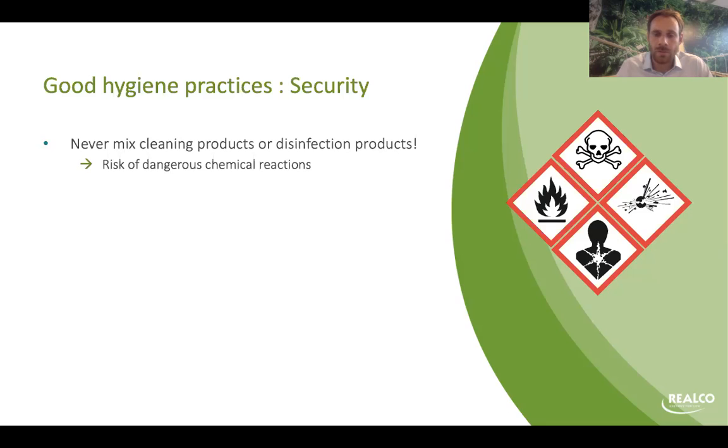I was following a factory, and they were cleaning 2 different lines. The lines were separated, but they were using 2 different chemicals for each line. And they were saying, yeah, there is no problem because it's 2 different lines. But the problem is that all the foam was going down into the drain, and in the drain the products were mixing. So, as I said, you may produce some steam, or some gas, with those reactions, and it can be really dangerous for the operators.